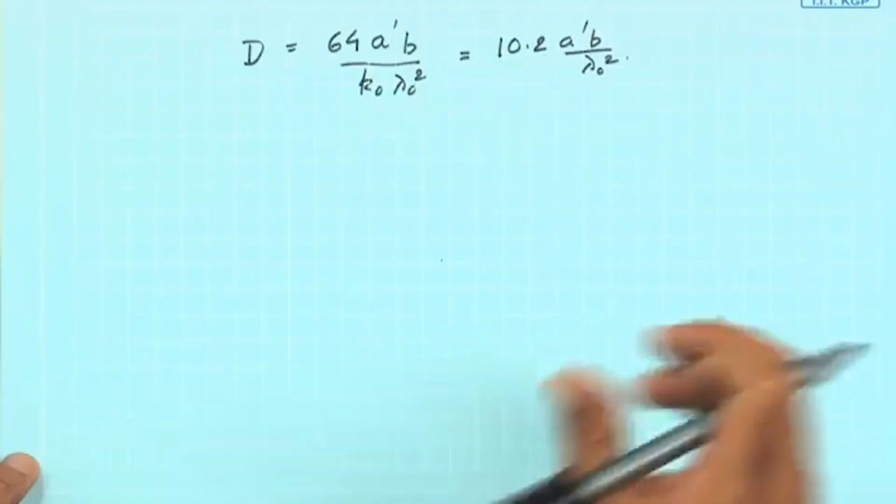But with the increase in the aperture, because if I increase the flare angle the aperture will increase, the extra gain somehow compensates the loss from the phase error.